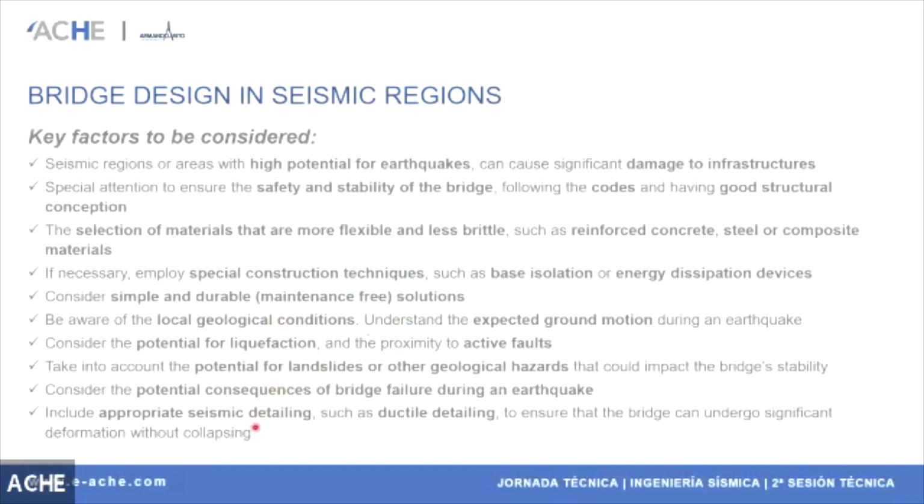Appropriate seismic detailing. Yes, very important when you're designing mostly reinforced concrete bridges. You have to take really good care of the detailing of the reinforcements and how to design your bridge to undergo the deformation without collapsing, because you accept the deformation, you accept the plastic hinges, but you don't accept that the bridge will collapse.